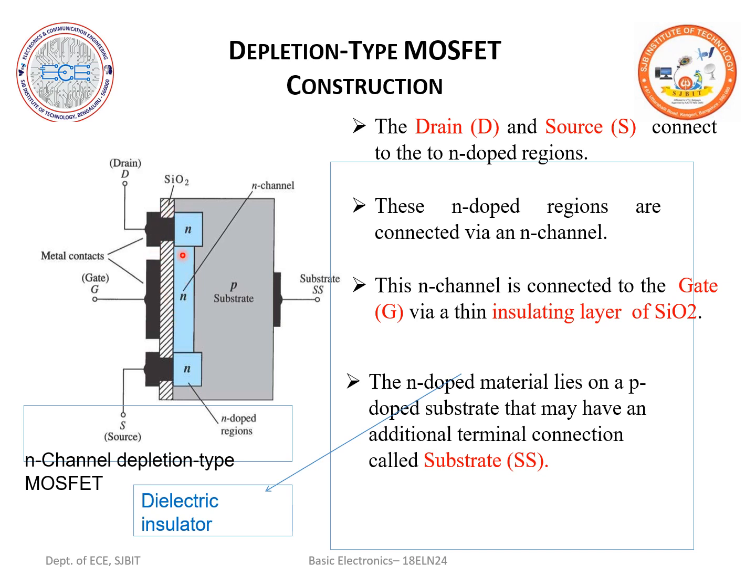An oxide layer of silicon dioxide, which acts as an insulator, covers the entire p-type and n-type regions. By etching the proper openings through the oxide layer, metal contacts for source and drain are made, right? So source and drain are made. The gate contact is formed on the surface of the metal oxide layer.